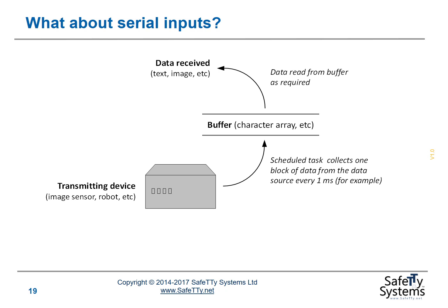You may need to consider either what we call a quasi-TT solution that we'll look at in a later session, or consider a fully event-triggered solution for your design. Before you do that, we'll look at a couple of other alternatives. But in many cases, again, just as we could with the data outputs, we can deal with data inputs using some form of hardware buffer.